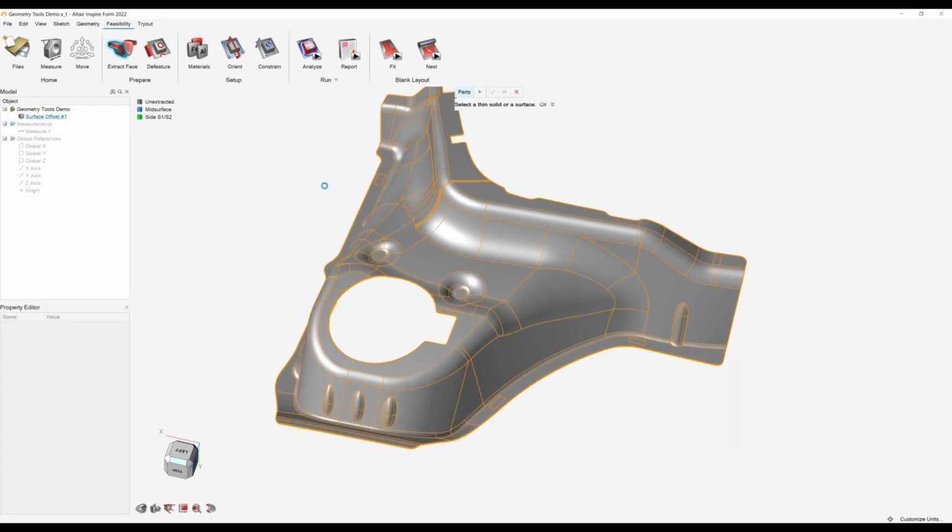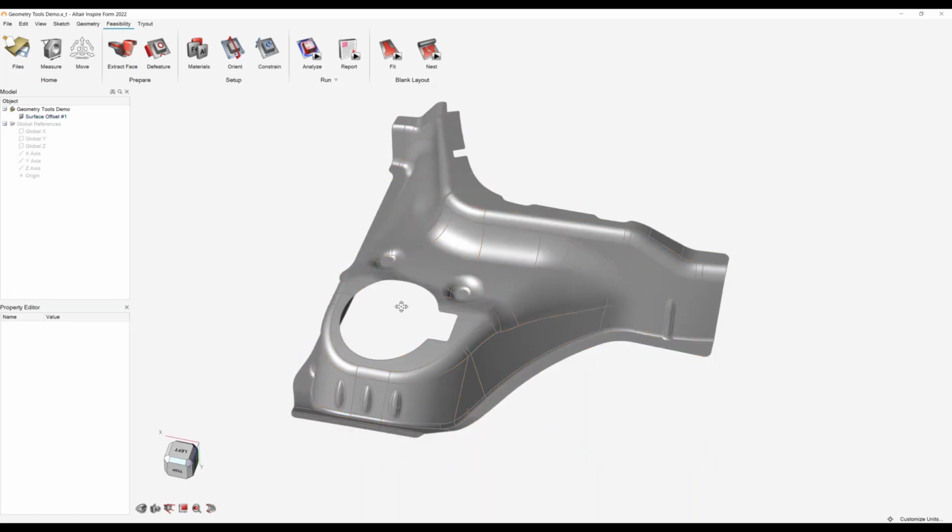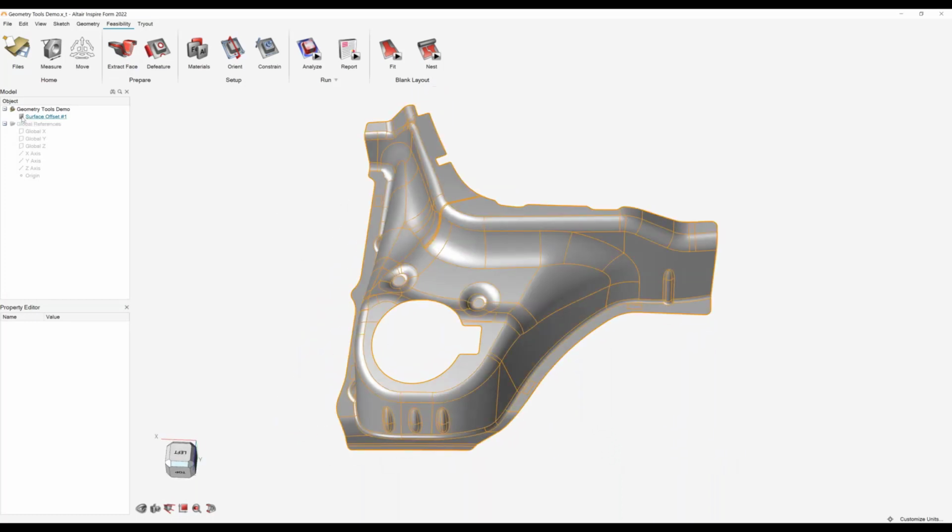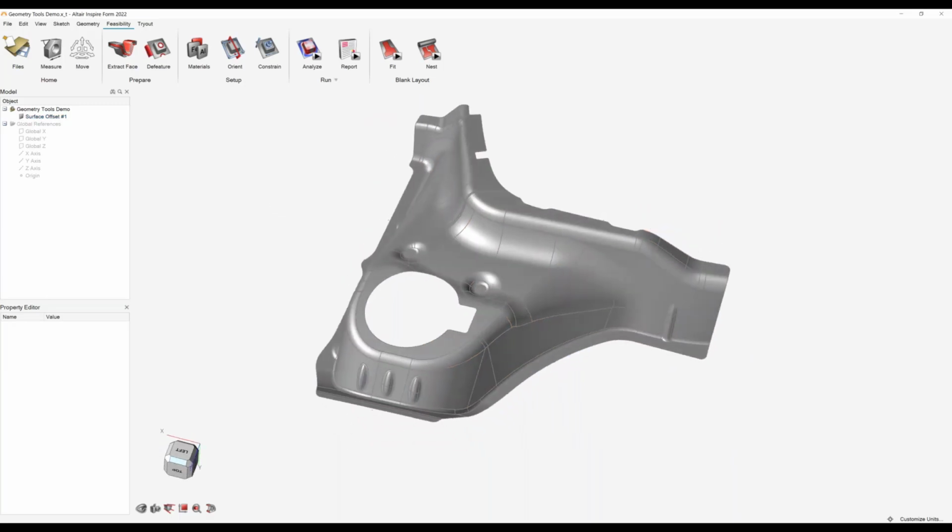I basically click on the part, and this will just convert this into a surface. So this is obviously the material thickness. So obviously it knows that it's 1 mil, and then we can choose the mid surface. I'm just going to hit the tick box just to accept that. And this will change this from a solid into a surface. Okay, so now I'm working with a surface, and we can see again the symbol's slightly changed in the tree on the left hand side, so we've now got a surface symbol.